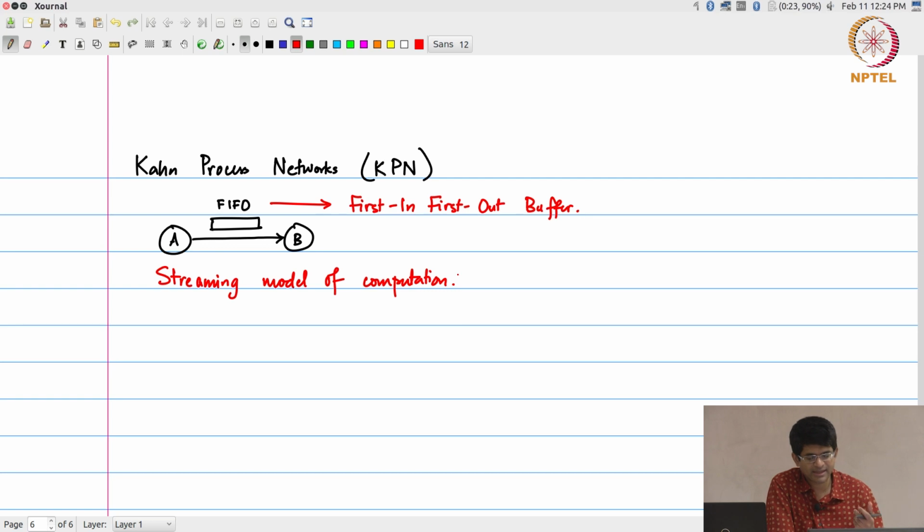In this case, if I have just two computational elements A and B, the assumption is that they communicate by means of this FIFO buffer. Anytime that A computes something, it generates an output and puts it into that FIFO buffer, and B can then read from it and do something with it. Which fits exactly with our notion of tokens in the data flow graph. In the data flow graph I was marking those D's on the edges and saying, these are tokens. How would you implement it exactly in terms of communicating FIFO buffers?